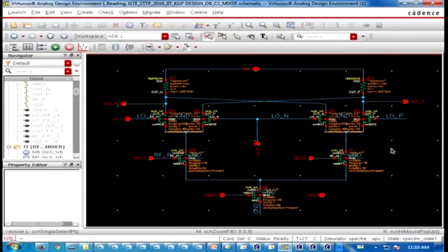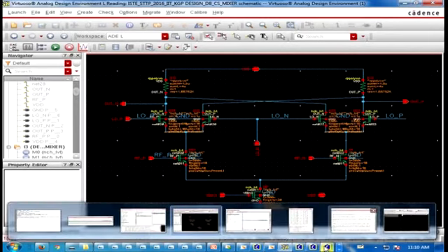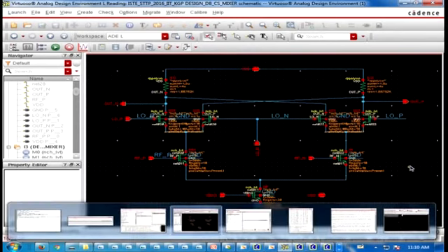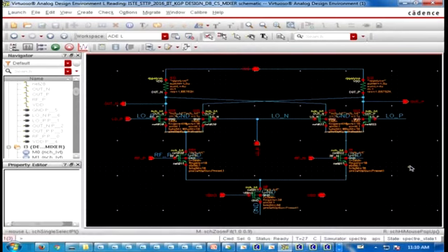Just these two, R1 and R2 for a Gilbert mixer. With small variations of that, if it is 800 ohm, I am getting those third, fifth harmonics peeping up. So please be careful about this resistance. These two resistances are the culprit for the design. Very careful.